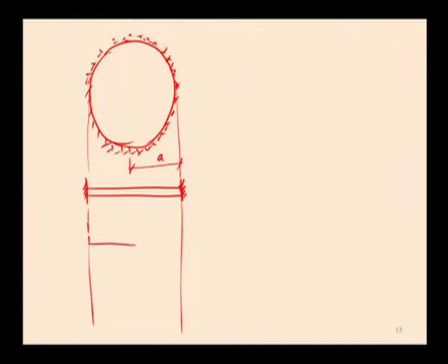So, here in the case of the partially fixed slab, there is a circumferential moment at the edge as well as at the center, that is the m theta diagram. Circumferential moment. So, here at the center it is 2 by 16 W A square, at the edge it is 1 by 16 W A square.